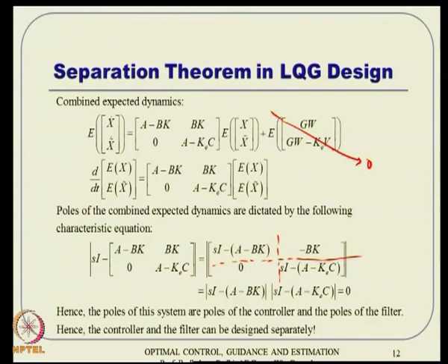And even the controller, even if you design it in a linear system setting, typically the implementation will involve at least some sort of gain scheduling. Gains will be interpolated, they are time varying actually. So, in that sense it is also a nonlinear control design. And in that setup, many successful results have been reported. You do not have to doubt or be afraid about that. But the fact of the matter is that something like the separation theorem is not there. So, just bear that in mind actually.